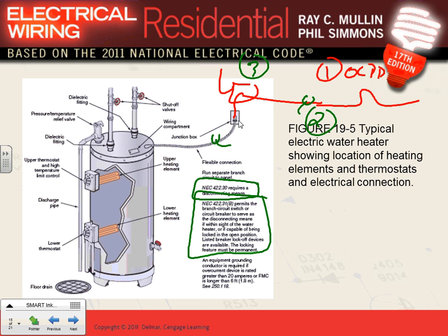But there's an alternative way where we could have avoided the disconnect and have a circuit breaker with a mechanism of locking it. But it has to be there at all times, not portable ones. You have to have an equipment ground conductor with it, and the flex cannot qualify, especially given the limitation up to 20 feet. If you're using a flex, the flex can't qualify as an equipment ground conductor if it's more than 6 feet, and if the overcurrent device is more than 30, which is 99% of the time, since your water heater is a minimum of 30. So you still have to pull an equipment ground conductor with your flex. Any question, guys, electrically speaking? Can I have a thumbs up, Chad? We know how this works electrically.